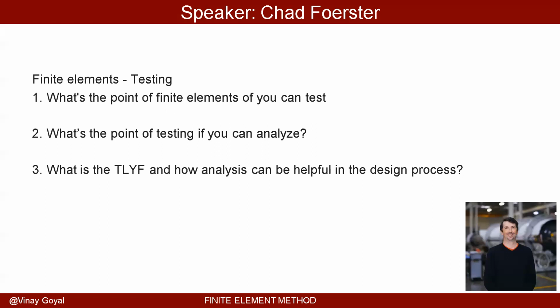Coupled loads analysis is that final model with all the different boundary conditions, running through transients and really coming up with the max loads that drive the design of your structure, because your structure is going to be designed for probably a specific load case or maybe two, and then it's going to be covering all of the other load cases. And so the finite element modeling helps you verify that and make sure you have coverage on the test. So testing is expensive, so you don't want to repeat it a bunch.